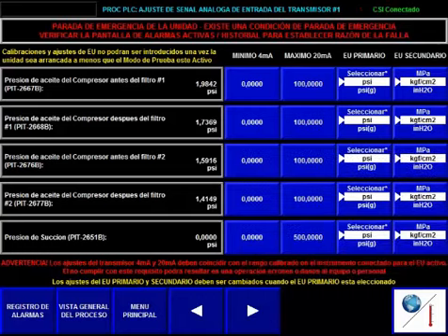On this page, you can see trips related to the compressor oil pressure. We have a low of 50 alarm, shutdown at 45 indicated in red. These are class B1 timers, which means it will be armed and the alarm will go off after the B1 timer expires, which is 15 seconds after the motor starts.